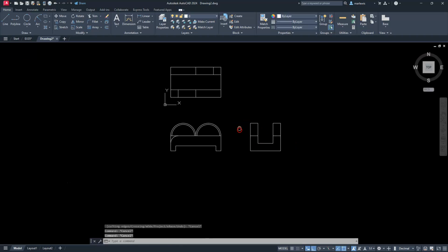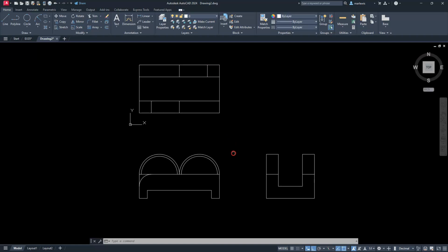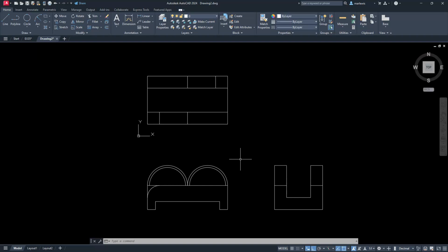Okay, so my drawing really doesn't have any hidden surfaces right now. That's going to be up to you to decide if you want to put the hidden surfaces on or not, right? We can't dimension to hidden surfaces, so sometimes you'll see drafters or designers leave their drawings like this, but if it's something relevant that you really want to show, you can put those hidden surfaces in. But for now, let's leave them off, and when we get to the drafting portion, we will put those hidden surfaces in.